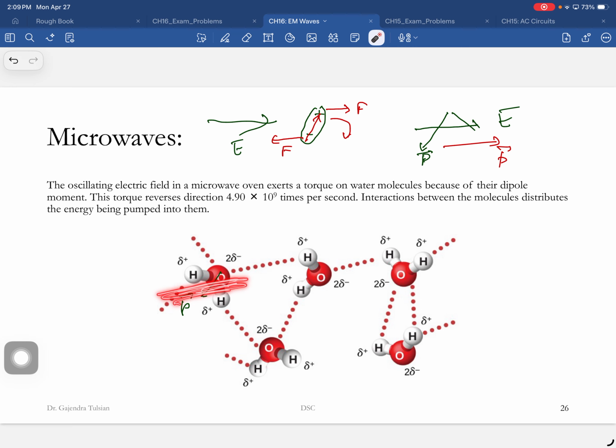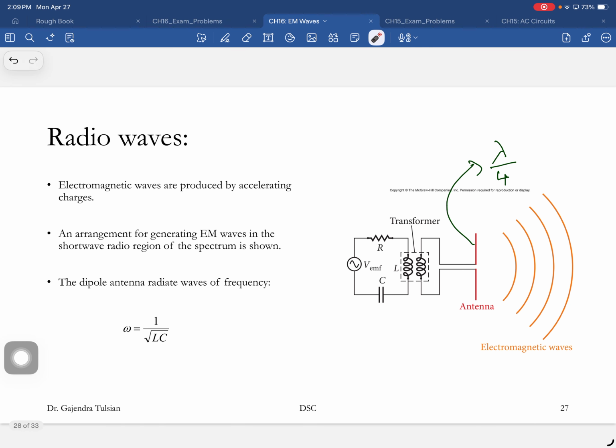And so this is showing you the dipole antenna. The intensity is maximum in this direction, and the intensity is 0 in that direction. So the intensity is proportional to sine squared theta divided by r squared. And so if this is a radio station and you're hovering right above it, you get 0 signal. If you're in a helicopter above the radio station, you get 0 signal.